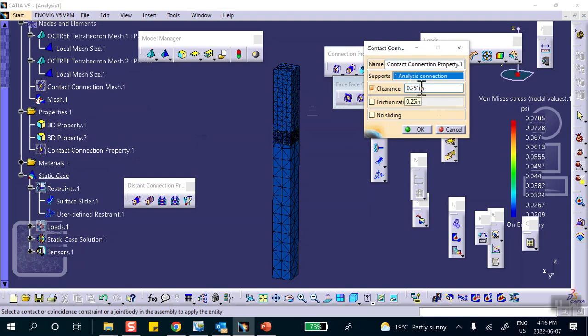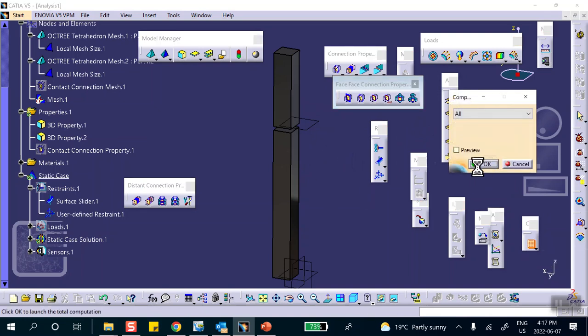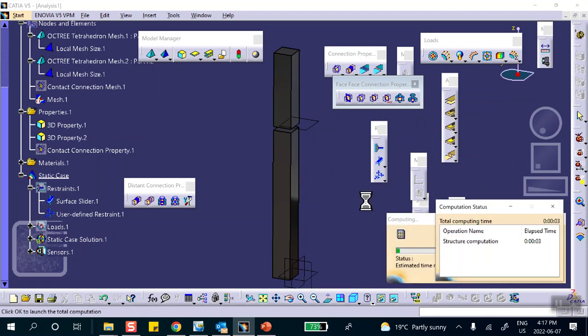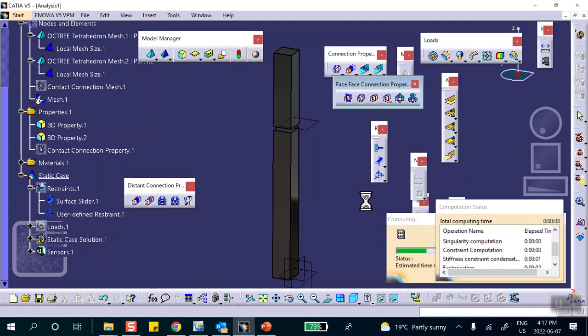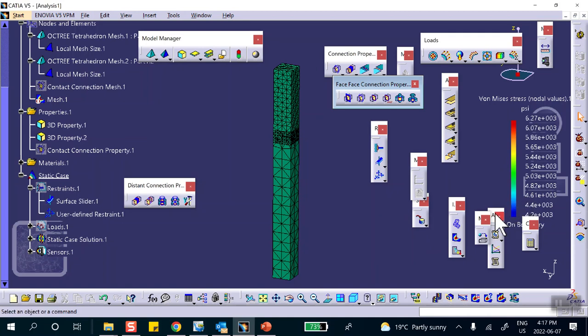So this is actually 0.249. That's what I meant. 0.249. Okay. So the clearance is 0.249, and we're pushing this thing down by 0.25, and now we should get non-zero values for stress. Okay, let's run it. We get huge values, of course. Well, huge values in the sense that pushes it down, but so right there, big values.